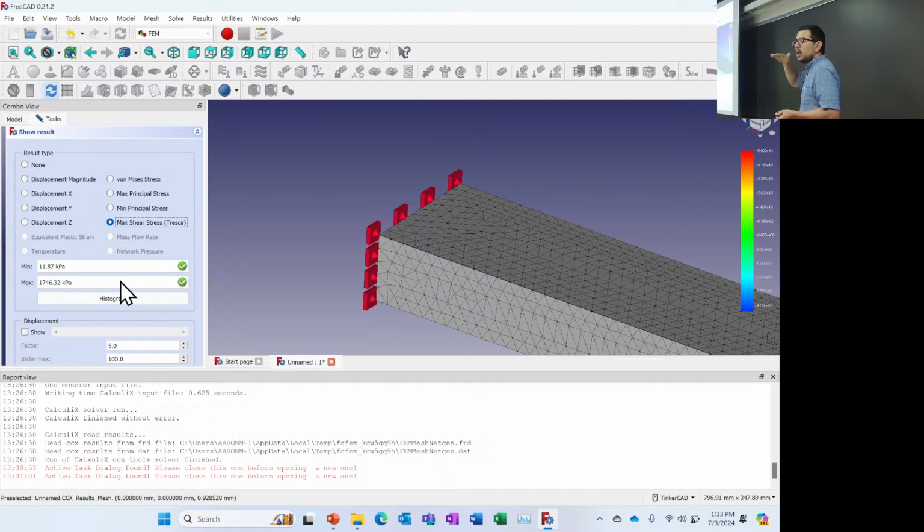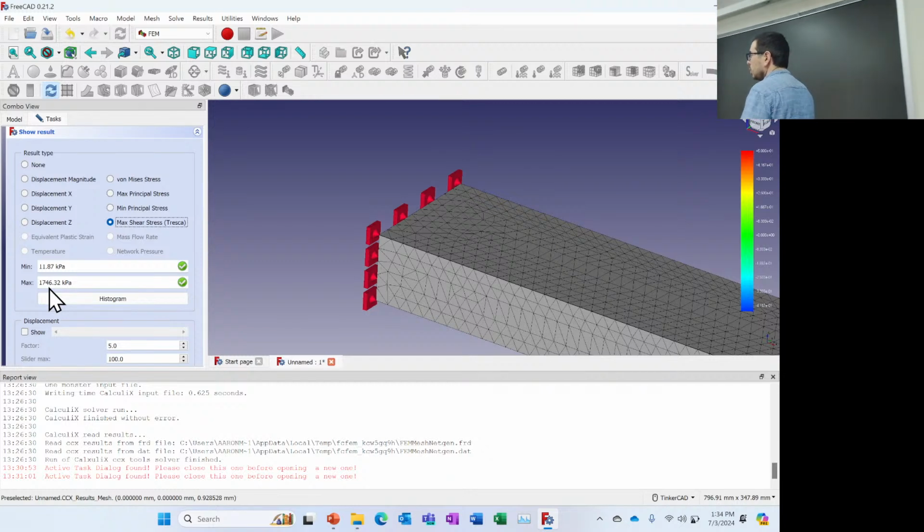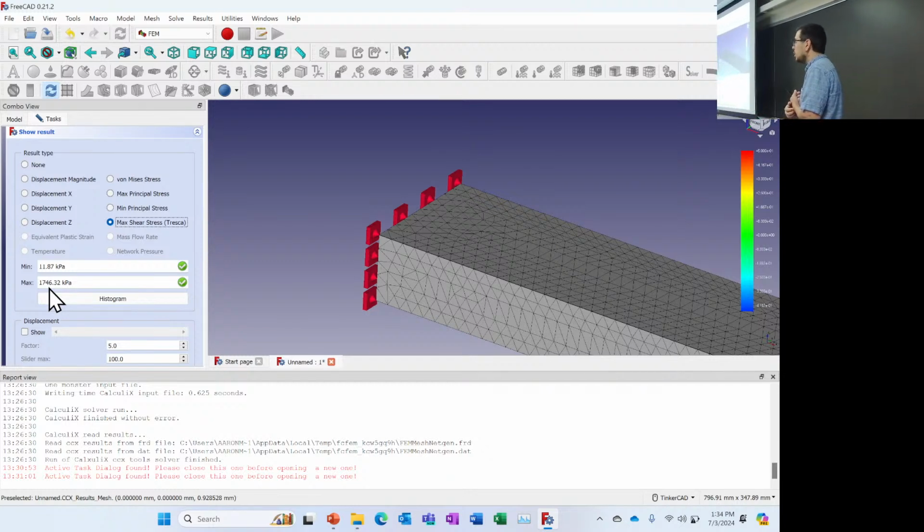So if I have uniaxial loading, what is the equivalent maximum shear stress? Well, we use Mohr's circle. Mohr's circle says that you've got sigma 1 equals something, and sigma 2 and sigma 3 are equal to 0. So that means it's just the radius of Mohr's circle, and the radius is sigma 1 divided by 2. So once again, this is going to be 1.7 megapascals, and if you double that, that's about 3.4 megapascals. Any questions on this? Any questions or thoughts?